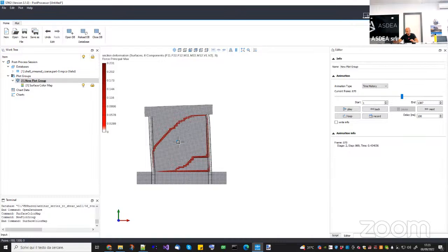For example, when I was doing my PhD, I was working on masonry. There, the microstructure is even more important because it's much larger. And when you model the microstructure, it was very easy for the crack in masonry to develop, and it gave a very nice prediction. The problem is that if you do a homogenization of this, and you use a very fine mesh, which is much smaller than the brick, the crack prediction will be linear.